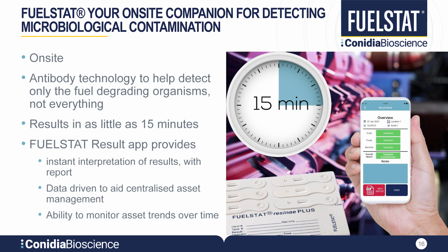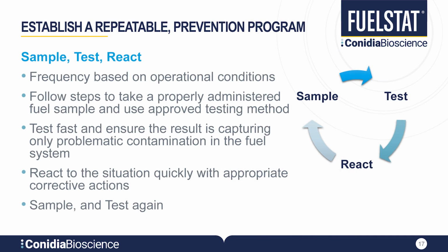All right, as I mentioned, there really is no one-size-fits-all approach to fuel testing. There are no legislative mandates for the testing and treatment of fuel, and many industry protocols vary. For instance, large parts of the aviation fuel supply chain cannot even use biocides. So the basis upon which any organization builds a prevention process rests on each operation's individual conditions.